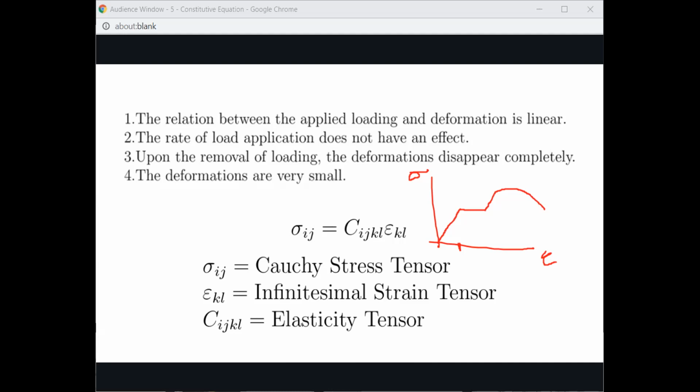Sorry about that. Okay, so let's go back. Here we experience elastic behavior. Okay, and it's linear. Okay, this is the elastic region, and here we start to yield. Okay, so here we have no increase in stress, but we still elongate.